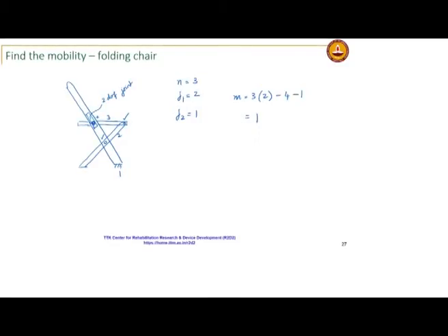Okay. So, you need to be able to recognize the connectivity of the joint correctly. The pin in the slot is something that throws most people off, that is why I did this example. Okay, that is a joint with 2 degrees of freedom.